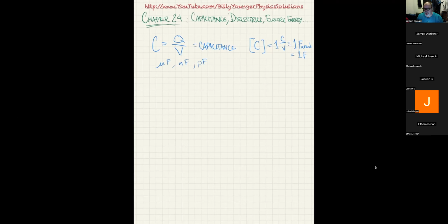And I told you guys coulombs are huge amounts of charge. It's not abnormal for a lightning strike to have a few hundred coulombs of charge come through it. So a coulomb is a big thing. In fact, if you ever find a 1 farad capacitor that's either not hooked up in a circuit and does not have the 2 terminals connected to one another, then stay away from it, because it's probably accumulated enough charge that it could hurt you really badly, if not kill you.